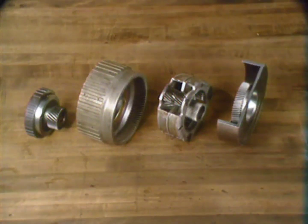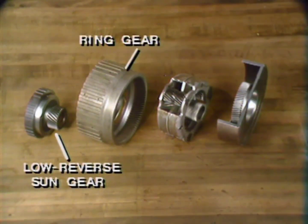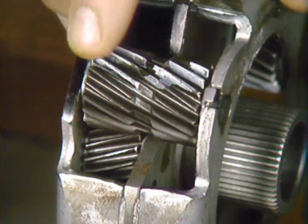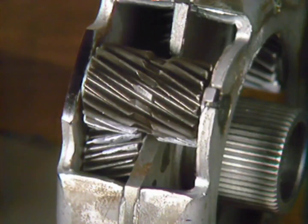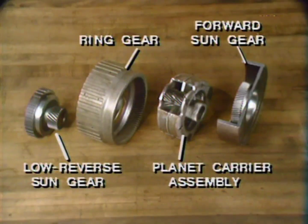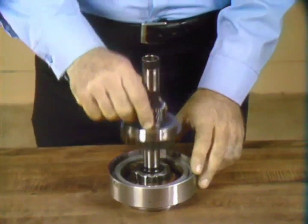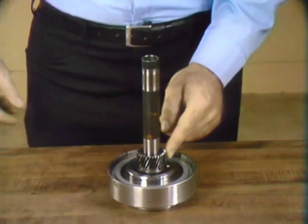Now we will look at the main planetary gear train parts, which are the low reverse sun gear, the ring gear, and the planet carrier assembly with two sets of pinions, 3 long pinions and 3 short pinions. Notice that each long pinion meshes with the short pinion and the forward sun gear. There are two ways to get power into this gear train. First, through the turbine shaft, the low reverse sun gear.